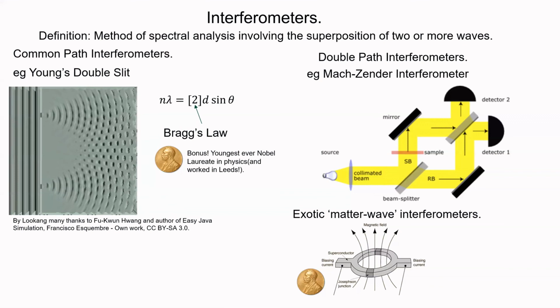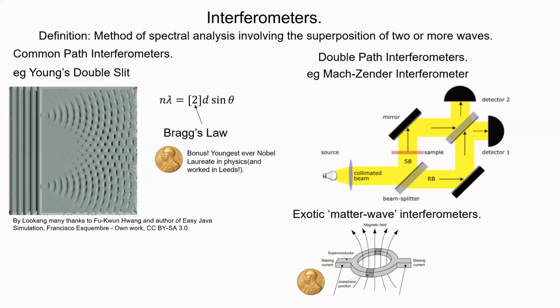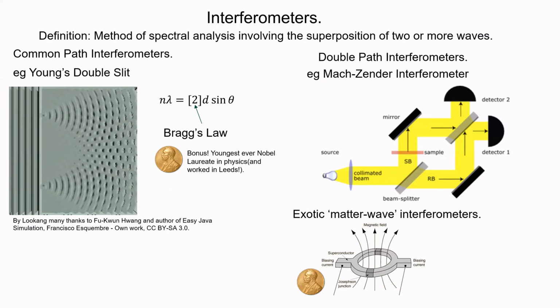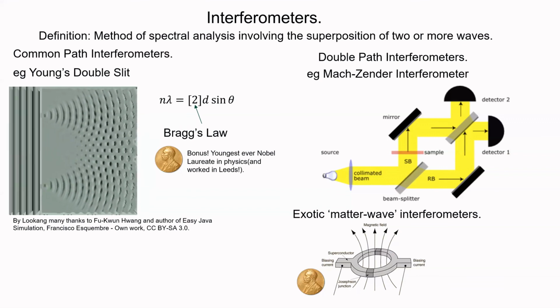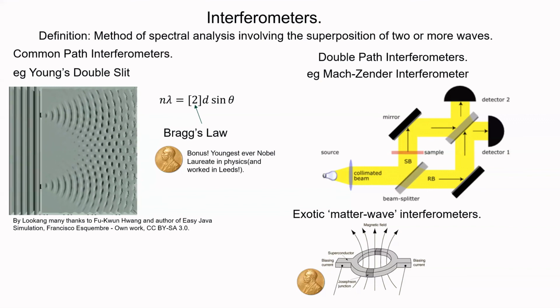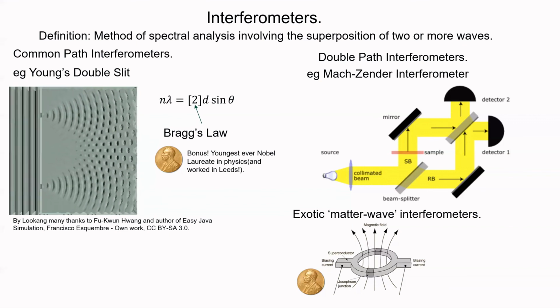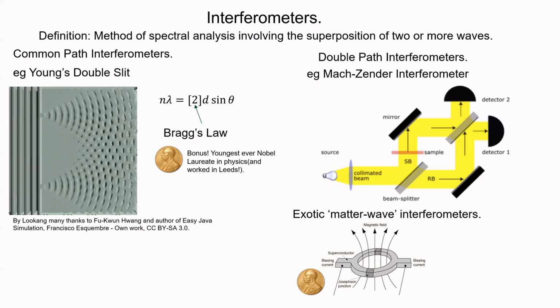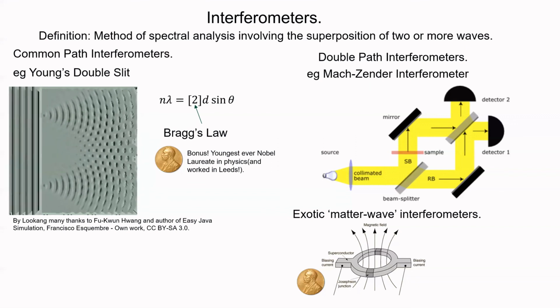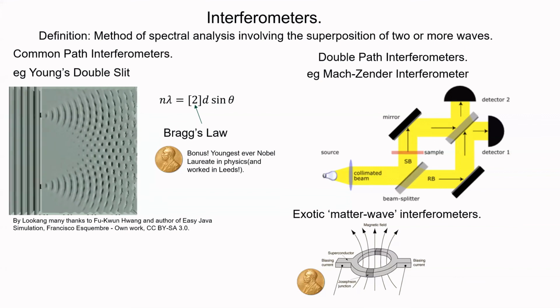And that not only means you have a very, very sensitive magnetic field sensor, so it can detect things like the magnetic field changes due to the neurons in your brain firing. It's that kind of level of sensitivity. You can also use it in other ways. For example, you can make a very sensitive current sensor, because if you place a little coil above it and have a current flowing through that coil, then that produces a magnetic field which couples into the SQUID, and then you detect that magnetic field with your SQUID. So it becomes this incredibly powerful sensor, which is all just using the same basic concepts of interferometry that we got from the Young's slits experiment.